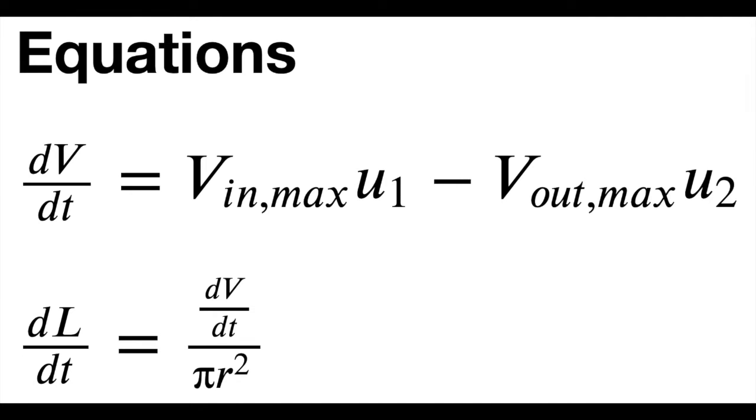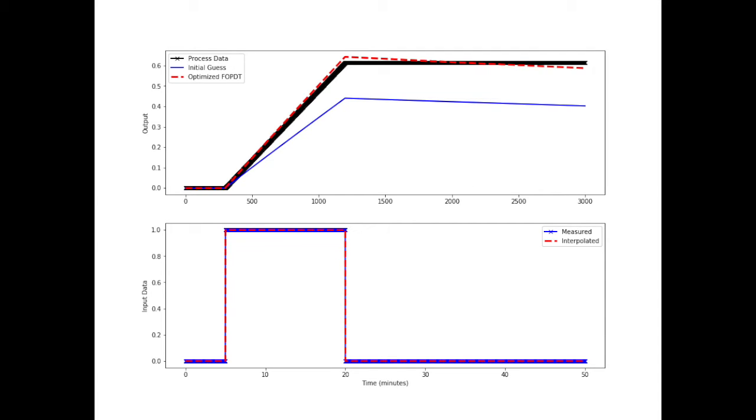In order to accomplish this, we decided to build a simulation for the tanks because we're still in the process of purchasing our equipment. To do so, we used a material balance for the water going in and out of our tanks, as well as adding powder at a certain point halfway through filling the tanks. We used this material balance model to create a simulated data set, which we ran a step test with so that we could fit a model to it.